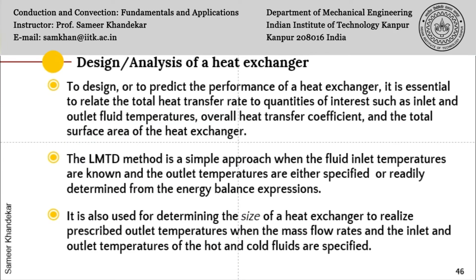So what do we mean by design or analysis of a heat exchanger? To design or to predict the performance of a heat exchanger, it is essential to relate the total heat transfer rate to quantities of interest such as inlet and outlet fluid temperatures, overall heat transfer coefficient, and the total surface area of the heat exchanger. So when you do the sizing problem, you are actually predicting the surface area, what will be the total area required, or what will be the length of the tube required to attain a certain heat transfer.